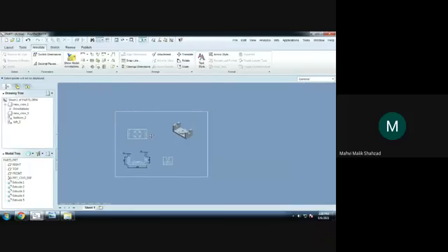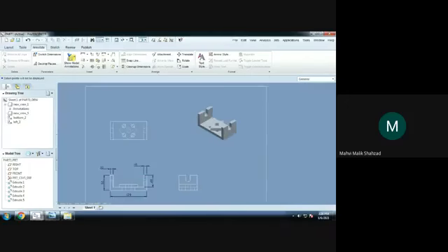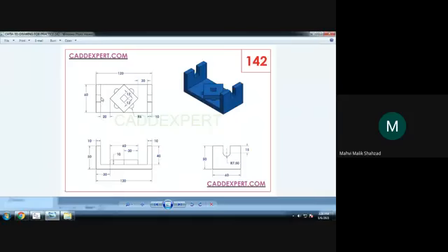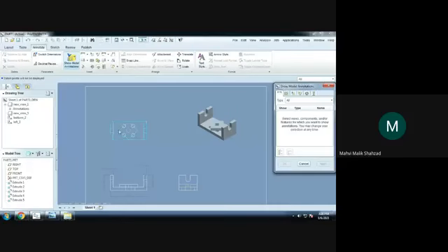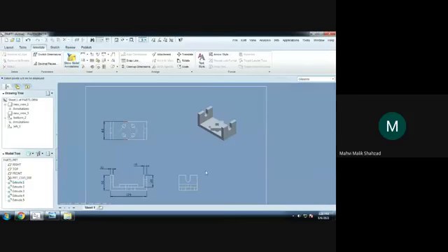Then same way, we'll go for the top view. So I will see the drawing. In this view, these are the dimensions which are given two times, 120 here, again 120 here. So we can create those dimensions. I'll go for this, show model dimension. I will select this. I want this dimension. Click OK.